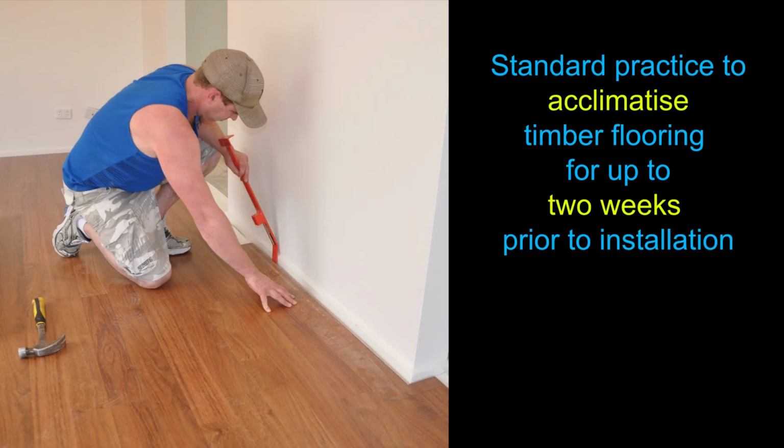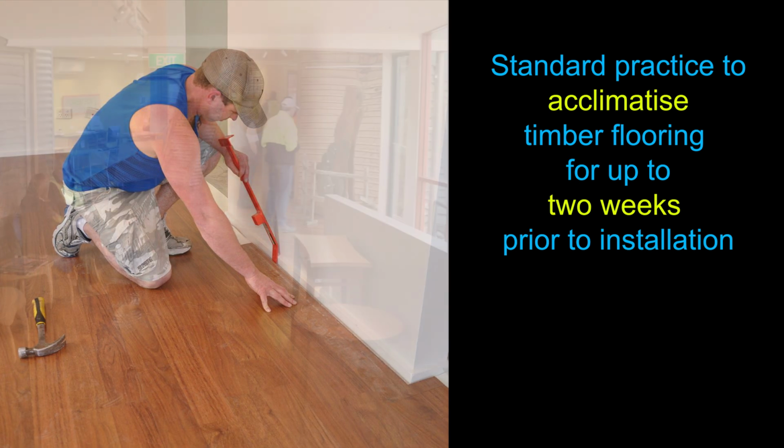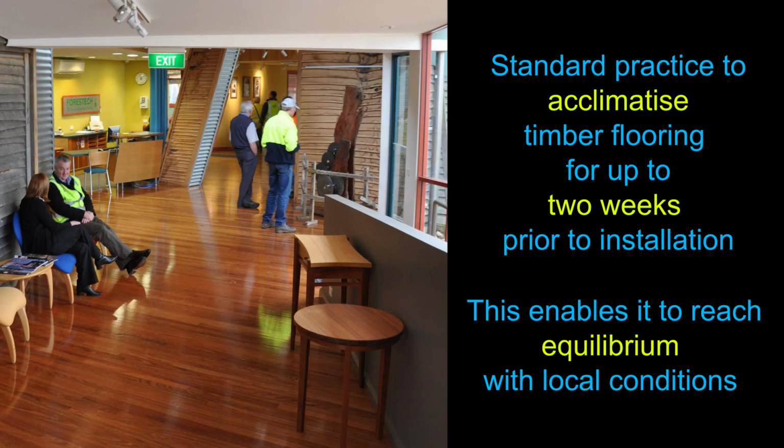Even then, it's still standard practice for flooring installers to acclimatise timber flooring in the room it will be installed in for up to 2 weeks before the material is fixed in position. This enables it to reach equilibrium with the local atmospheric conditions, which might be drier or wetter than the normal MC range.